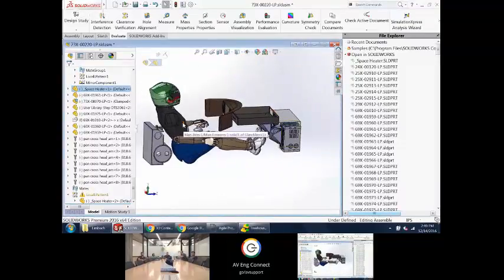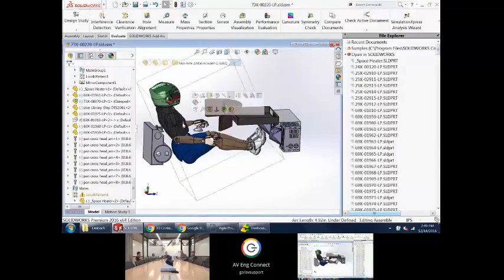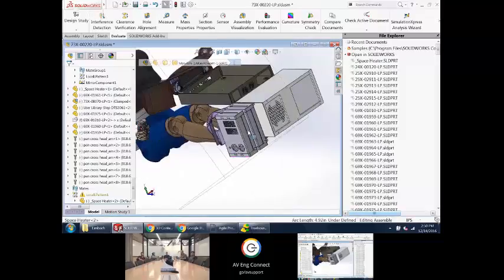But just by hitting Save As, it created a part file for me, but it didn't do anything to my subassembly. I have to go in there and say, okay, swap this out. But that's how you can do it. You can right-click a part or an assembly and switch them out with either a part or an assembly. You can mix and match. When it asks you to select the new faces to replace the mates, I always get confused on... You're selecting them on the part that you put in. Also, if I hadn't just hit it so fast, it allows you to move the part out of the way. Because a lot of times the thing is sitting where it's supposed to be, and you're like, well, the faces I need to pick.